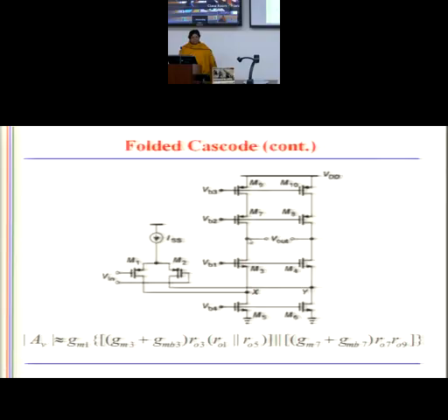So this is V out, a stack of 2 transistors here. This is M3 already there. Now this is 1 transistor. A 1 here, complementary, and then 2 transistors. This is your differential output. This you may replace by a simple current mirror or a cascode current mirror, whatever be the requirement.